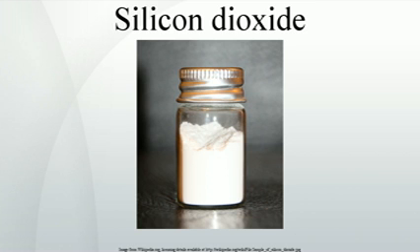Health effects. Silica ingested orally is essentially non-toxic, with an LD50 of 5,000 mg per kilogram. On the other hand, inhaling finely divided crystalline silica dust can lead to silicosis, bronchitis, or cancer, as the dust becomes lodged in the lungs and continuously irritates them, reducing lung capacities. Prior to new rules issued in 2013, OSHA allowed 100 micrograms per cubic meter of air. The new regulations reduced the amount to 50 µg/m³ down from 100 µg/m³. The exposure limit for the construction industry is also set at 50 µg/m³, down from 250 µg/m³.